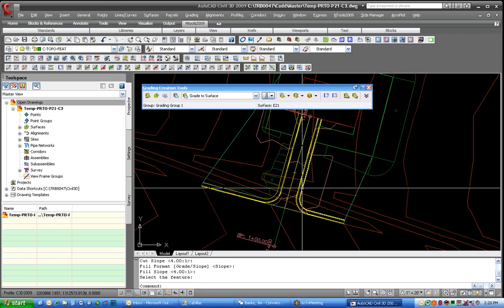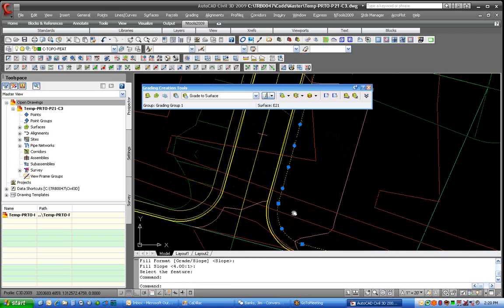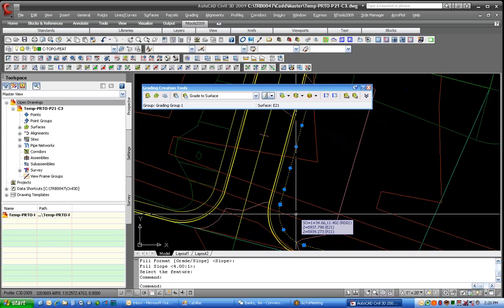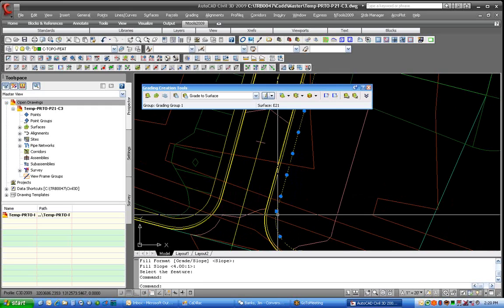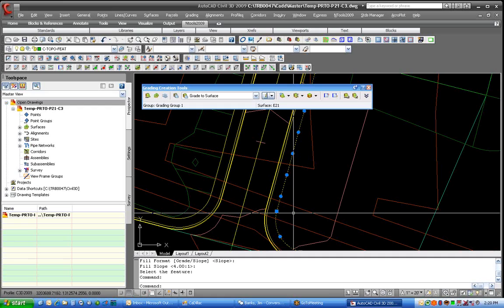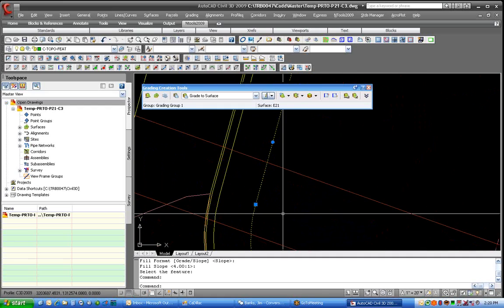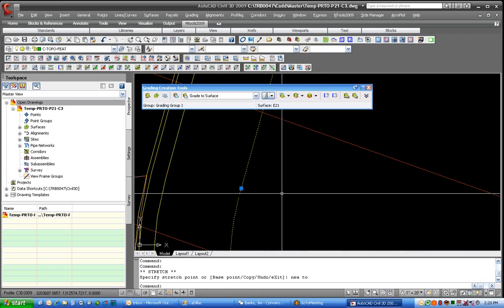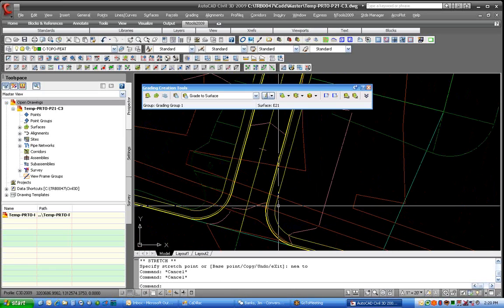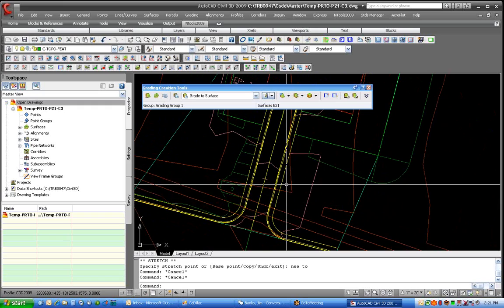All right. On the right side here, I've got a bug with this model. I played with it this morning, and it was unable to calculate a daylight off this feature line, and the reason is off this vertice right here where it samples. I think there's a vertical face or something going on in my existing surface that it couldn't figure out. So to fix that, I'm just going to kind of cheat and move that vertice over a little bit.